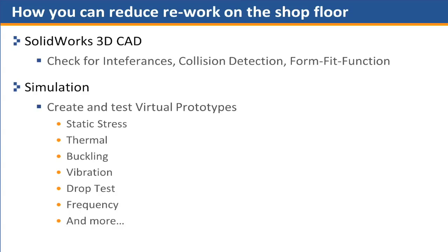A couple of key points on reducing rework on the shop floor. I put SolidWorks here because in SolidWorks you're going to be doing your design. You can check for interferences, collision, basically form, fit, function. You do that all inside SolidWorks.